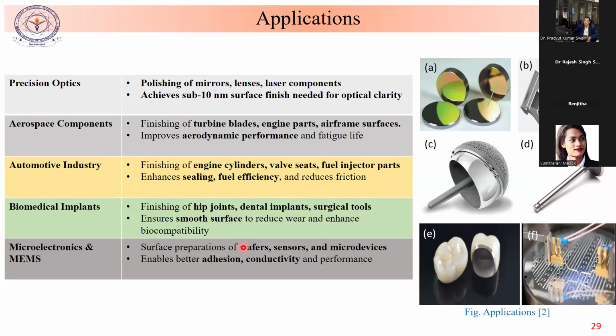So then how will we make it super finish? Super finish means we have to finish this to a level of at least less than 50 nanometer, sometimes 10 nanometer, and some people are giving results at angstrom level, in the surface roughness in angstrom, not in micrometer, not in nanometer, in angstrom. Then how will we do it?